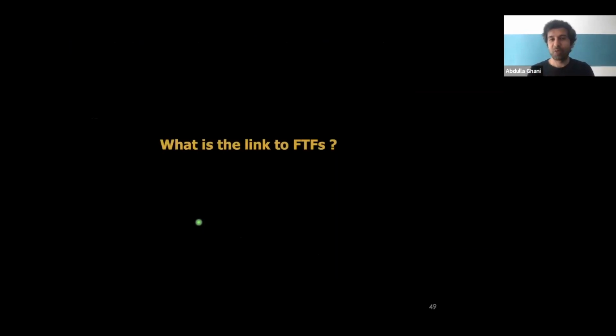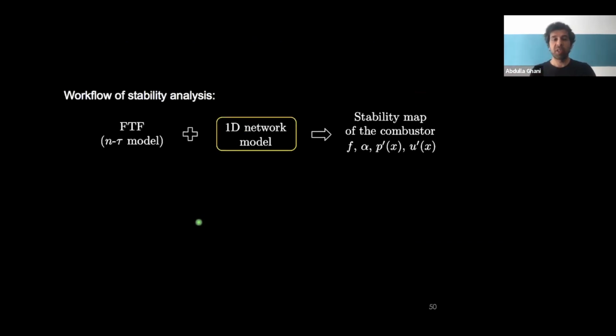So what's the link with the flame transfer function, you might say, because I want to talk about thermoacoustics. Think about the situation where you cannot obtain the flame transfer function. Let's say you don't have a loudspeaker to excite your flame. The only thing you have is perhaps an unstable combustion chamber. You have your limit cycle signal, which means that the flow naturally excited the flame. This is information that we could perhaps use. This was the sparking idea when I first started working in this direction.